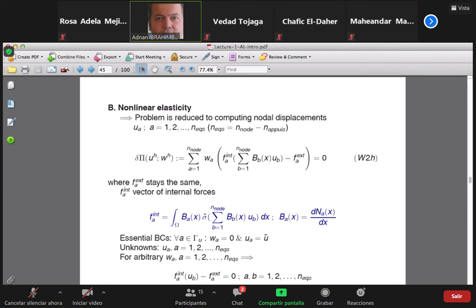This is a nonlinear function of my strain. And here, coming from the virtual displacement, or virtual strain, is this coefficient B. So in this particular case, I don't obtain a set of linear algebraic equations, but for nonlinear elasticity, I obtain a set of nonlinear algebraic equations. And then the goal is to obtain something called incremental analysis, to be able to show how you actually compute and solve such a problem.